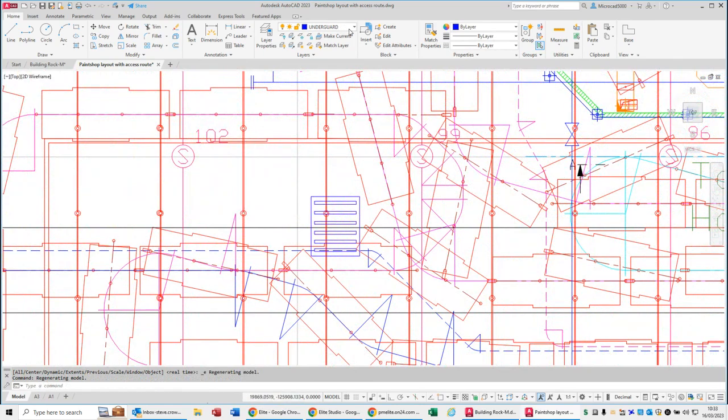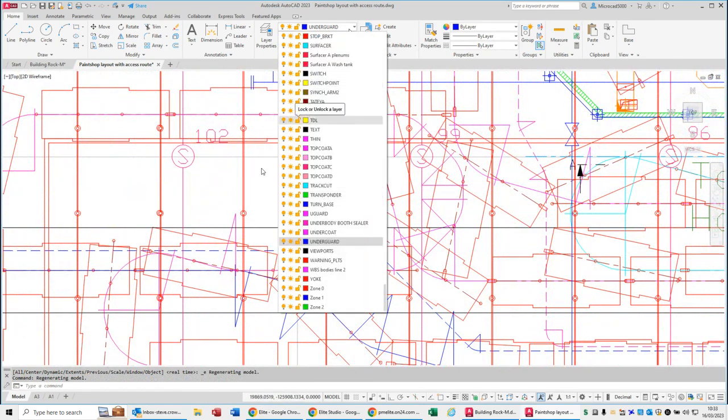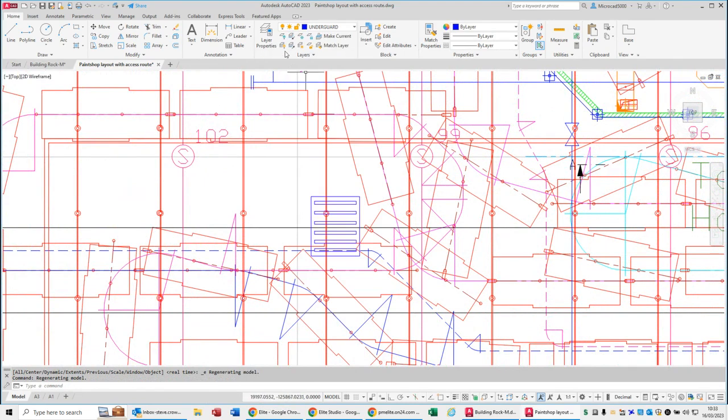Now, blimey. So I'm going to go through all this big long list here? What a chore. You can use this tool here, look. I'm going to pin that panel out. It's these two buttons here, look. So if I say isolate, it will either hide or lock all the other layers except for the ones of the objects I select.